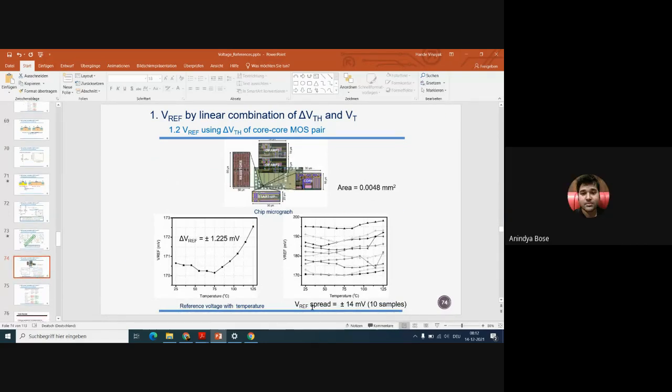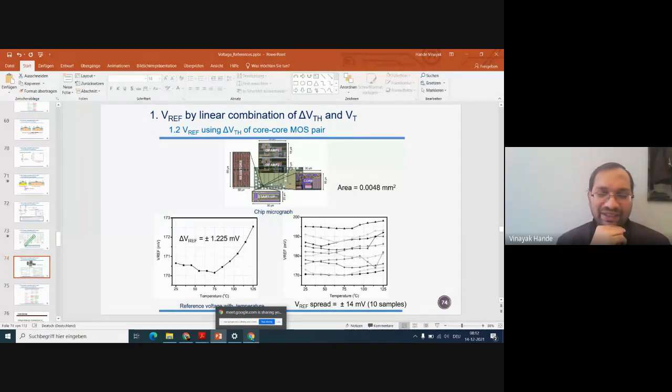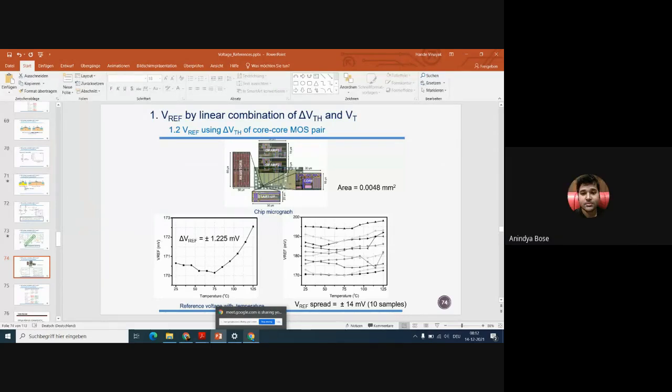And in fact, in 180 we have fabricated those concepts, so it's proven that it is working. I think it is only true when all other relevant parameters of the MOSFET transistor are constant, like NA, dopant concentration, and oxide capacitance. When all other things remain constant, then only I think this relation might be valid. Yeah, right. If everything is constant, then if you reduce the channel length, your VTH will increase. Yeah. Thank you.